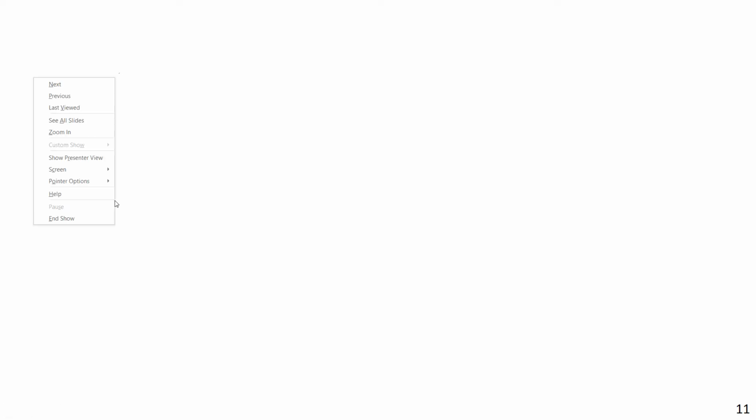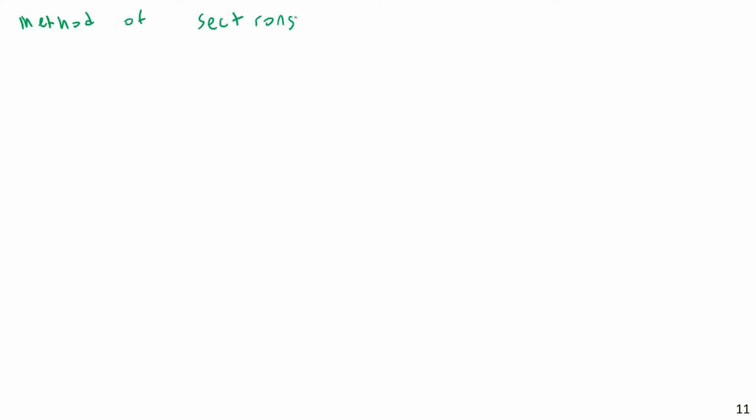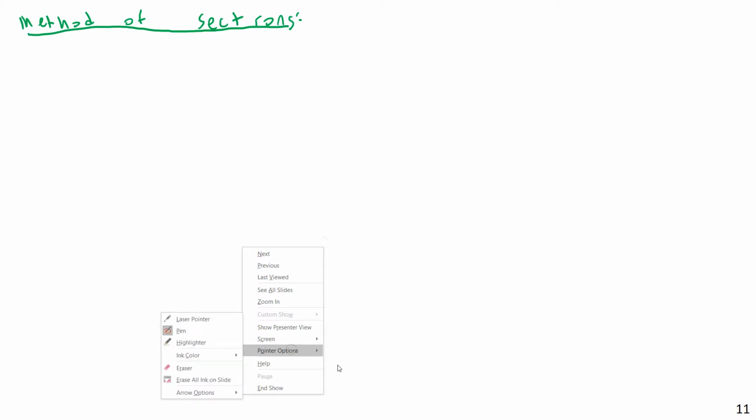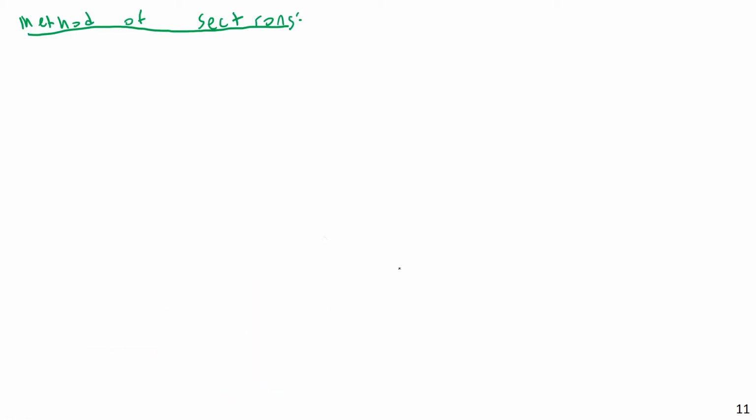Anyway, let me explicitly write out the steps of the method of sections. First, I generally recommend getting the external reactions on the truss if you can, because oftentimes you can get this, especially if the truss is simply supported or supported by only 3 reaction forces.